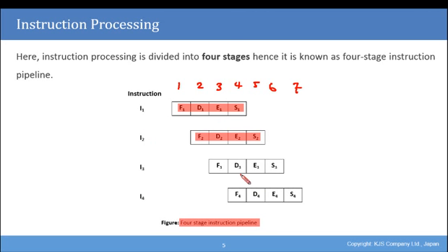And if this was to continue, as soon as the instruction 1 had finished, we could then start with instruction 5, I5, and this would be here, F5, and then D5, and so on. And this could happen on all 4 lines. So we could run I5, then we could run I6 out the back of I2, and I7 out the back of I3. This enables us to have a constant stream of instructions running to improve the processing of a CPU.